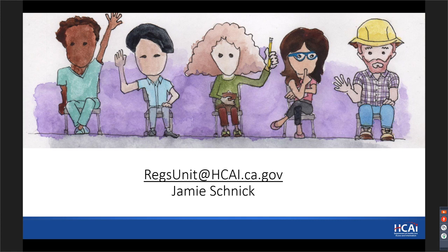We're trying our best. Next question reads, for GFCI protection, if the vending machine needs GFCI protection and it must be accessible, does this mean we need to provide GFCI breakers? Yeah, for it to be accessible, I hope we could all be in agreement that if it's behind the machine, the GFCI receptacles on the label say they should be tested monthly. The idea is that you're protecting the public from a ground fault.